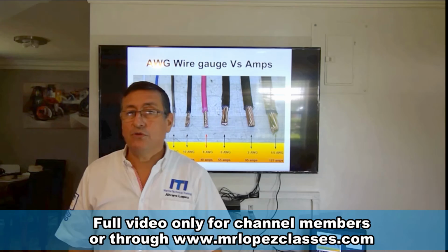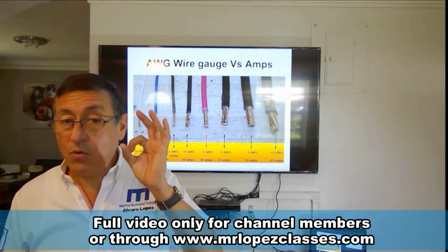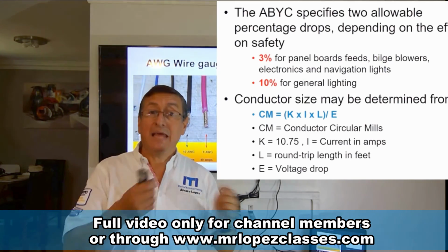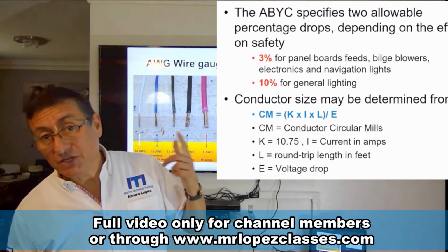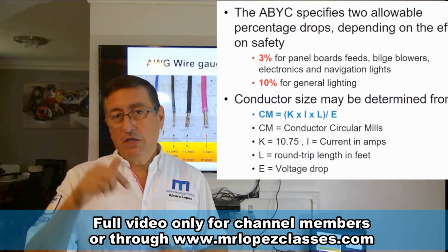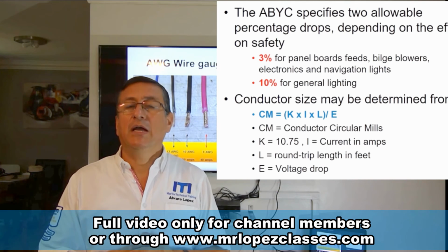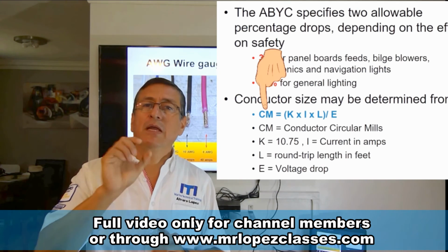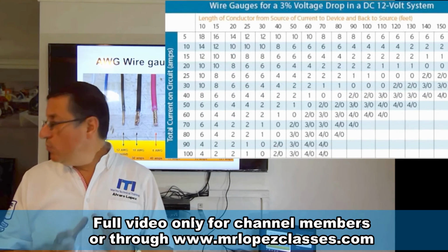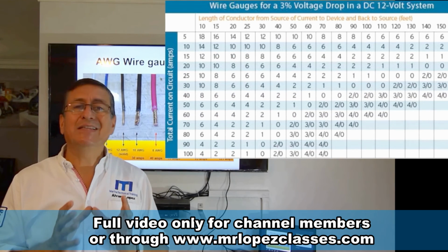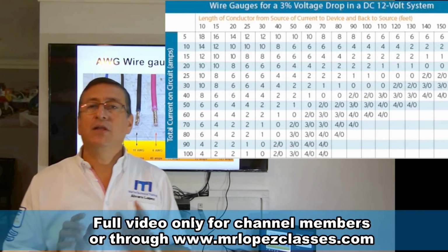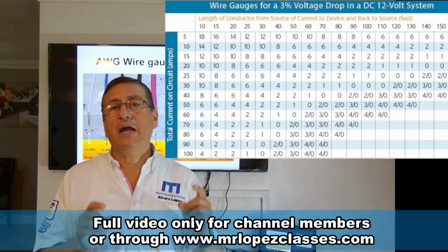Remember the procedure to calculate the gauge of the wires and select the appropriate wire. You remember chapter 4, conductors, okay? You can use this book, check chapter 4, and you will find the formula in circular mills to calculate the gauge of the wire. Or you can use the ABYC electrical study guide to select the table and to select the length of the wire according to the intensity.